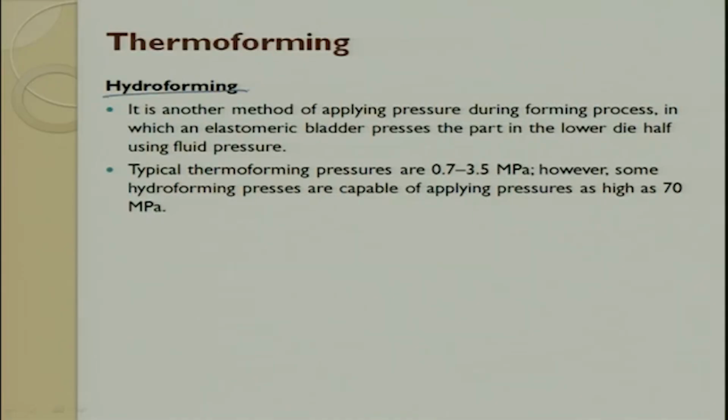What is hydroforming? You apply water at a very high pressure so that you consolidate to get the required output. When you push water, you have to put it inside an elastomeric bladder. So, the pressure is applied rather than putting a metal.